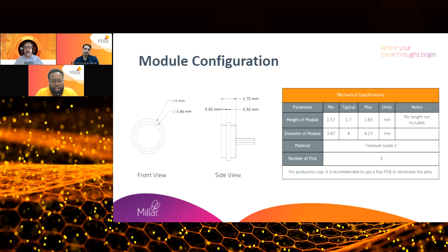Yeah, I think that's a really great question and points to an interesting point in that the TiSense sensor is not a standalone device, but more so a component that can be leveraged by device developers in order to achieve chronic pressure measurement. When compared to some of the other devices that were mentioned, ultimately, the capabilities are pretty much similar. We're looking to achieve chronic pressure measurements of disease populations and provide insights to physicians. But the way that we do that is a little bit different. The CardioMEMS device leverages a capacitive sensor in order to record pressure. The sensor within the TiSense uses a piezo-resistive sensor in order to measure pressure. Ultimately, capabilities are fairly similar. It's just different ways of essentially skinning a cat in this instance.